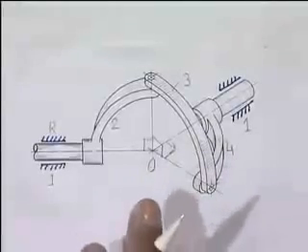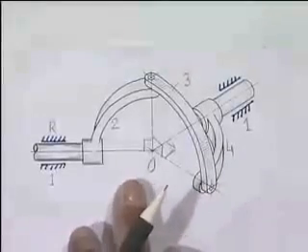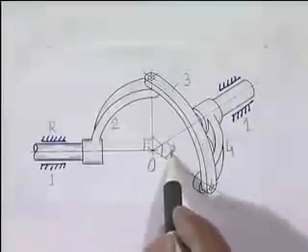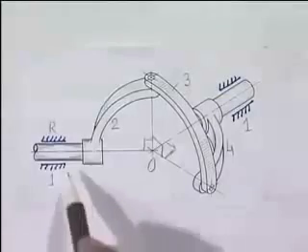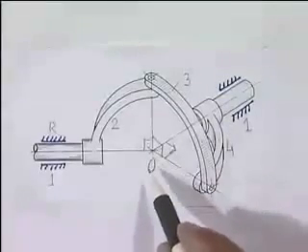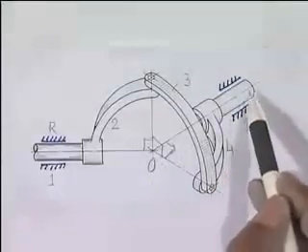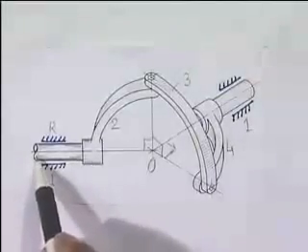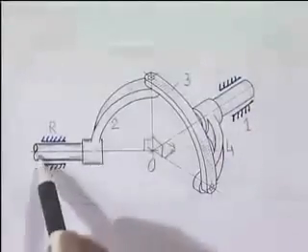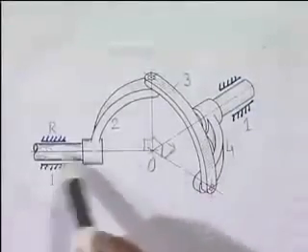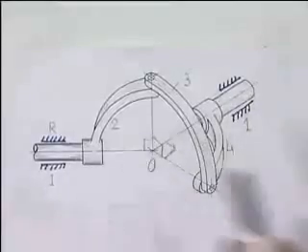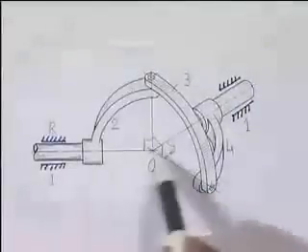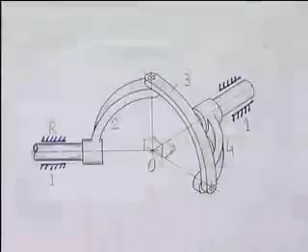So this Hooke's joint is a special case of a spherical mechanism or spherical linkage where all these angles are 90 degrees. And such a linkage, as I said, is used to transmit power from the propeller shaft which comes out of the gearbox to the input to the differential, and these axes are intersecting. As we see, the input and the output shaft, whichever is input or whichever is output, doesn't matter, these two shaft axes are intersecting at one point.